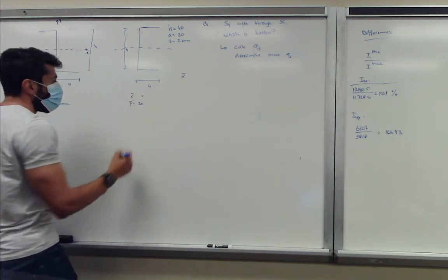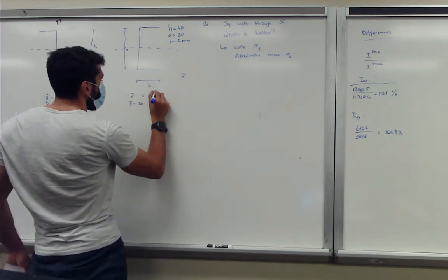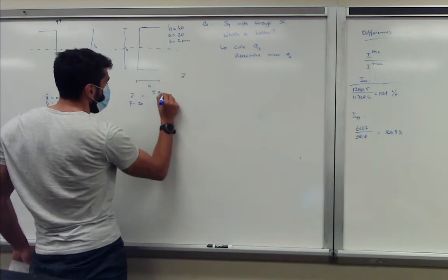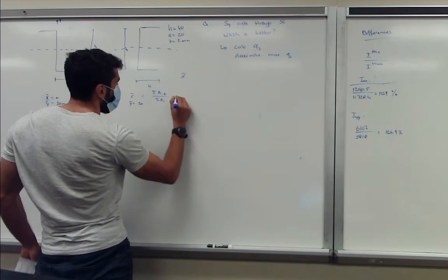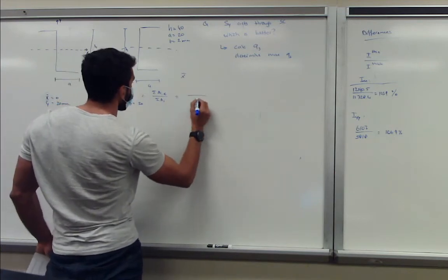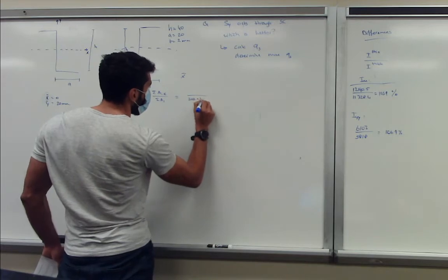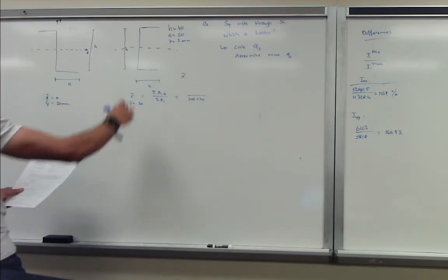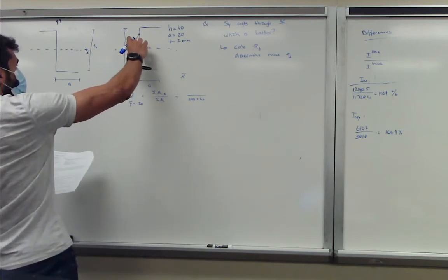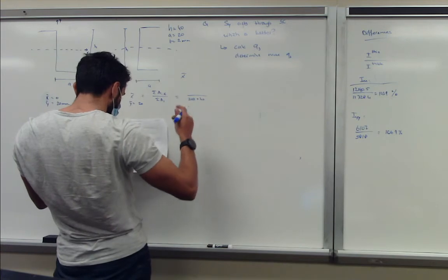So in this case, it will be, again, summation of areas times x_i over summation of areas. So in this case, summation of areas, I always start off with that. So that's 2at plus ht. And the bottom one will be 0, so you only have to determine the top parts.